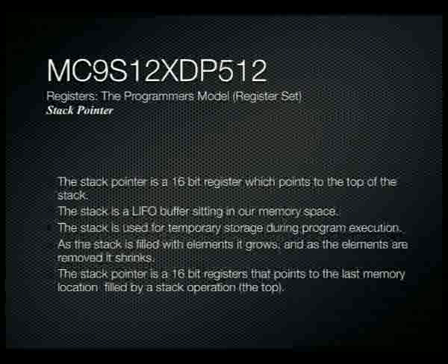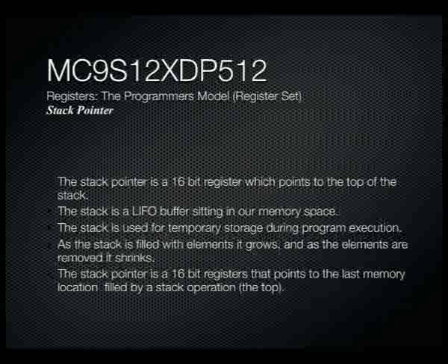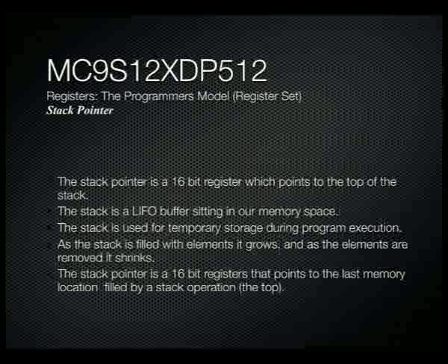Okay, the next register that I'm going to talk about is the stack pointer. The stack pointer is a great little register that effectively is a memory pointer which points to the top of the stack. A stack is a chunk of memory in our RAM that we use for temporary storage. We can push values onto the stack, and we can pop, or pull, values off the stack. So we have a stack pointer that effectively points to the top of our stack, because that's all we really need to remember is the top.